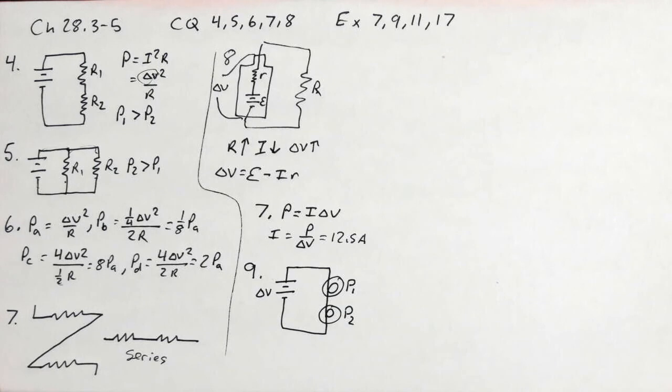That means it's assuming it's got 120 volts applied to it for that power rating. When these are hooked up like they are here, the power is different than that value. And it even could be bigger, but if it was, these would fry.